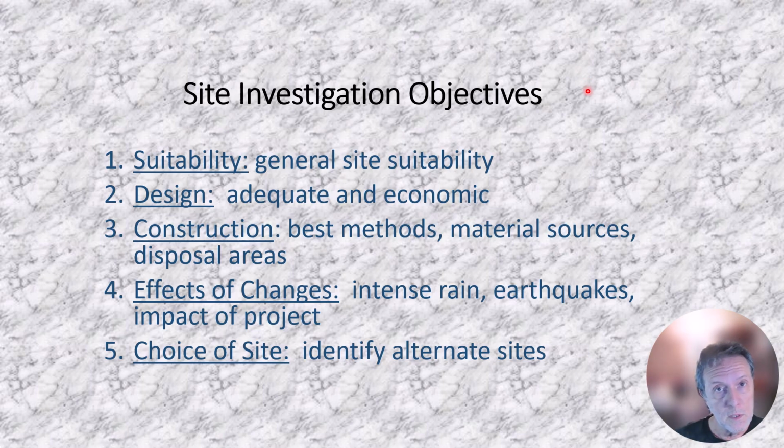Okay, so the objectives of a site investigation, I've probably touched on them just now. What is the suitability of the particular site to the project that's being planned? Is it suitable? Sometimes a site will have soil and rock conditions that are so cost prohibitive that it's not worth it. Let's say you want to build a small one-family residence, but find that it's situated on a huge landslide where you might have to excavate 40, 50 feet to dig out the loose material and restabilize the hillside. That's cost prohibitive for one small house, so that may not work.